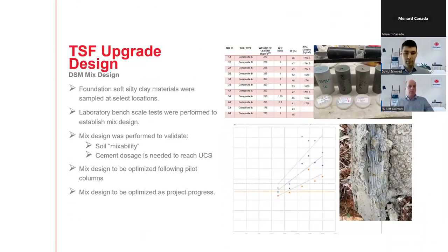The first step while doing soil mixing is to make sure that the soil can be mixed and can meet your performance criteria. You're building literally a natural concrete, so there will be variability in your results.